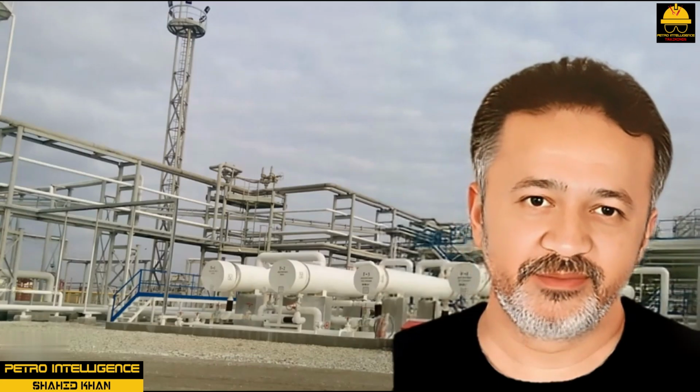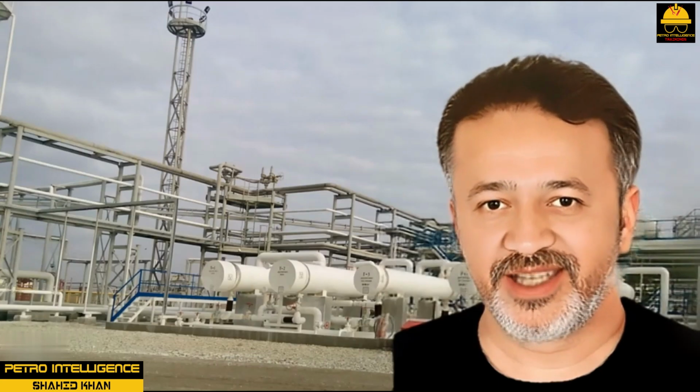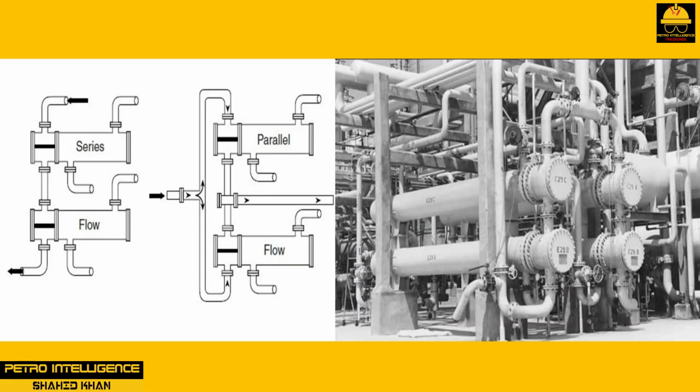Parallel and series. Flow heat exchangers can be connected in a variety of ways. The two most common are series and parallel, as shown in the picture. In series flow, as shown in the picture, the tube-side flow in a multi-pass heat exchanger is discharged into the tube-side flow of the second exchanger. This discharge route could be switched to shell side or tube side depending on how the exchanger is in service. The guiding principle is that the flow passes through one exchanger before it goes to another. In parallel flow, the process flow goes through multiple exchangers at the same time.